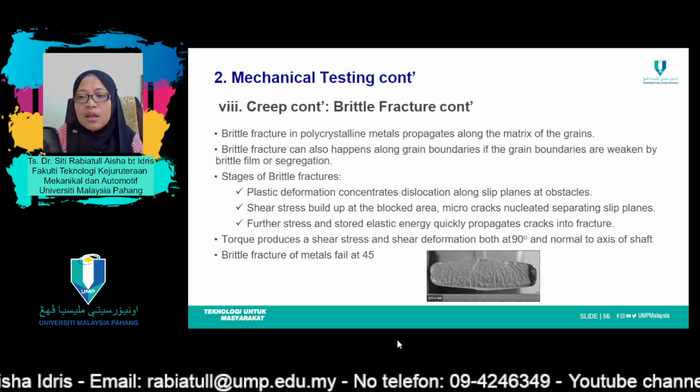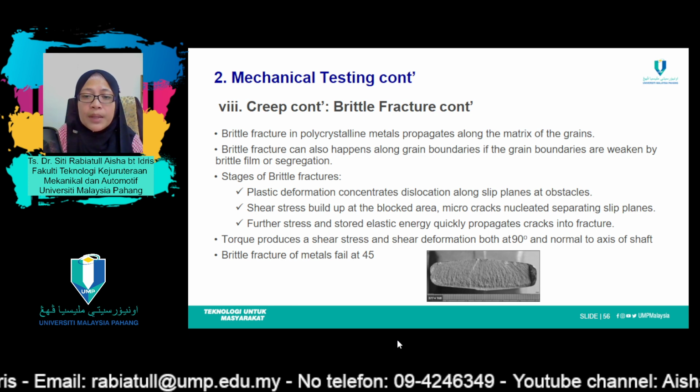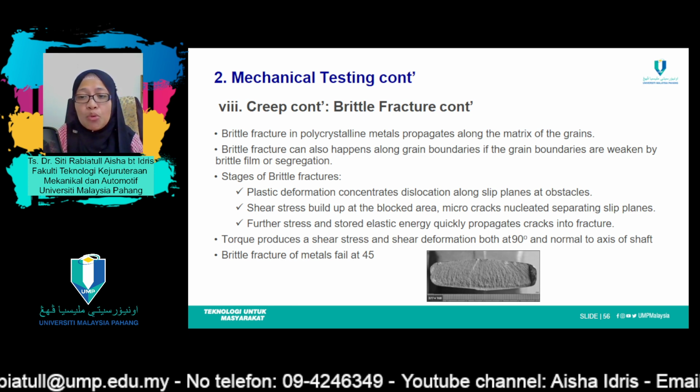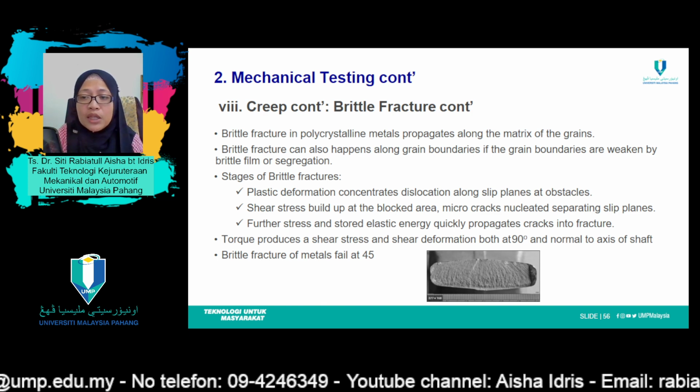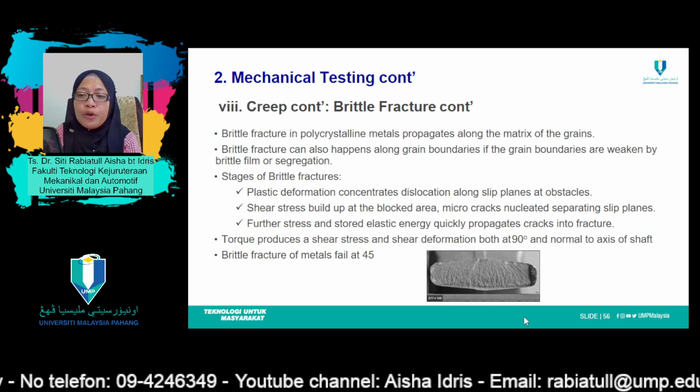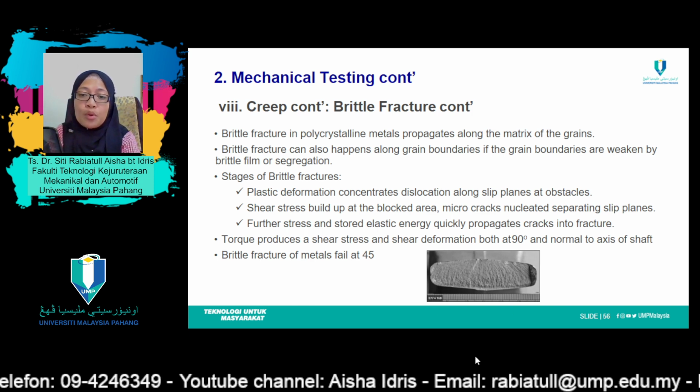Micro cracks nucleate, separating slip planes, and further stress stored as elastic energy quickly propagates cracks into fracture. And finally, this type of surface topography is produced.